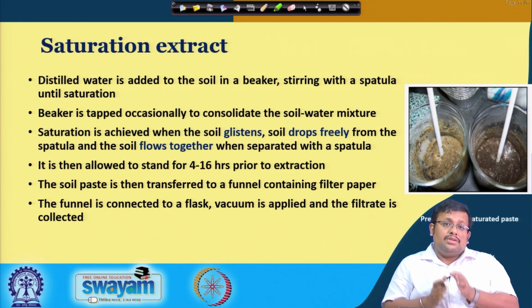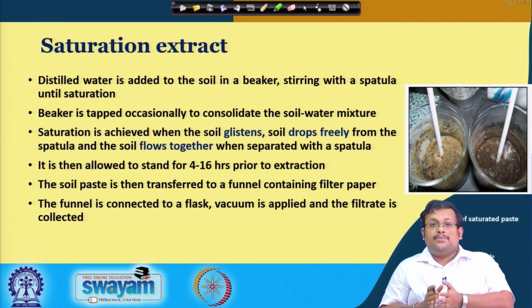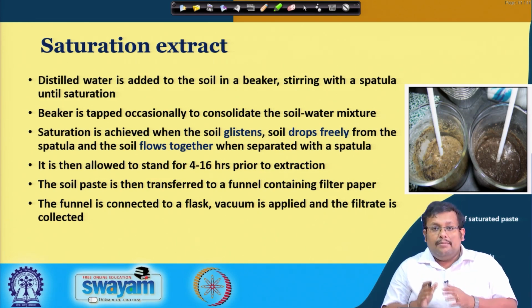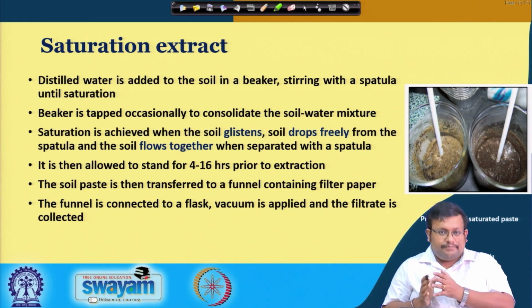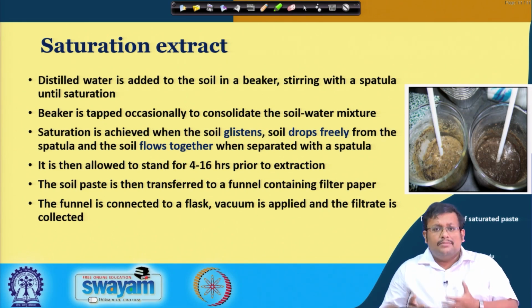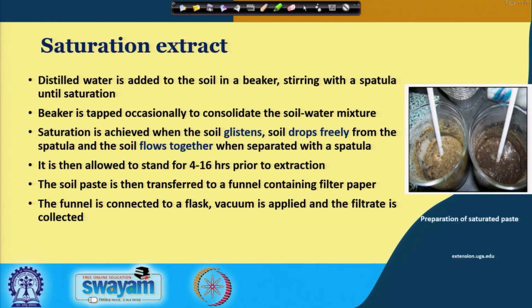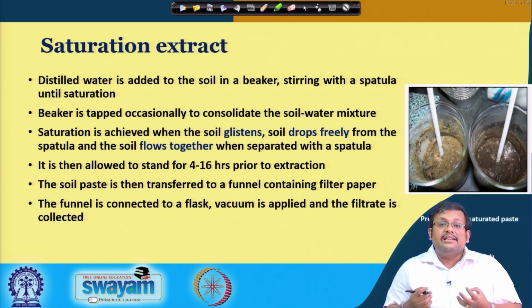and then it is allowed to stand for 4 to 16 hours prior to extraction to homogenize and also to equilibrate. The soil paste is then transferred to a funnel containing filter paper, and the funnel is connected to a flask. We apply vacuum, and the filtrate is collected.